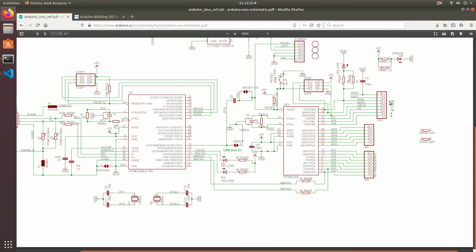So here is written the port as it is on the Arduino: 13, 12, 11, 10, 9, 8. And now you look where the line goes, and pin 13 goes right here to PB5. So that's the B port and the pin 5, and here we have from PB0 to PB5 all pins, and so we need PB5 here because that's where our LED is located.